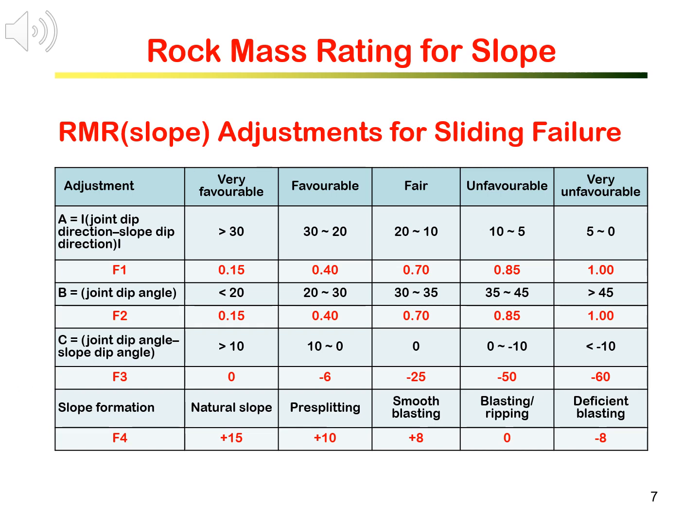Rho A is to calculate the angle between the joint dip direction and the slope dip direction. The smaller the angle between the dip directions of the two planes, the more parallel are the two planes. Since being parallel gives more potential of plane sliding, and this becomes unfavorable, it leads to the higher F1 value.